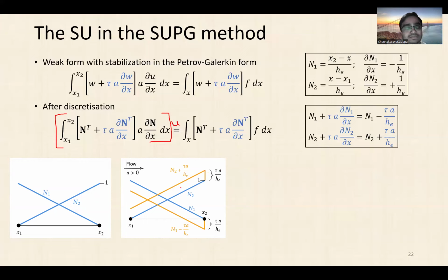So these are the plots of the new basis functions. What exactly is happening here? In order to understand, let's put one more element to the right side of node 2. So we have node 1, node 2, node 3, three nodes, and then let's plot the basis functions for both elements.